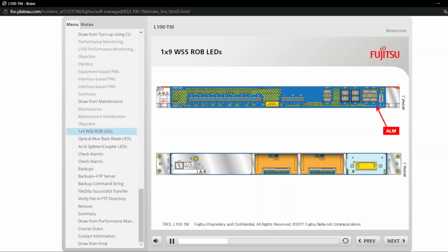OSC LED, for the optical supervisory channel. Off: normal operation or no power. Green: incoming optical signal operating normally. Red: input port is down, either E-SC-E1 or F-SC-E1. E1 LED, for edge port. Off: normal operation or no power. Green: incoming optical signal operating normally. Yellow: payload missing indication, PMI; high reflection, HREF; backward detect indication optical layer, BDI-O. Red: WDM loss of signal; WDM power out of specification.